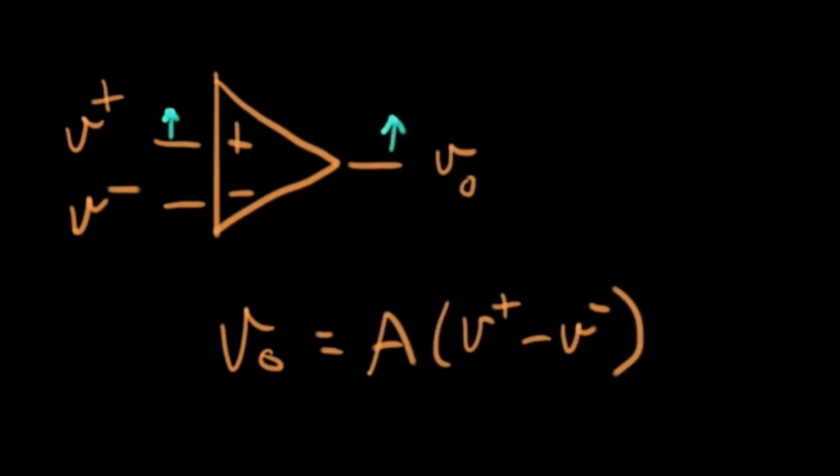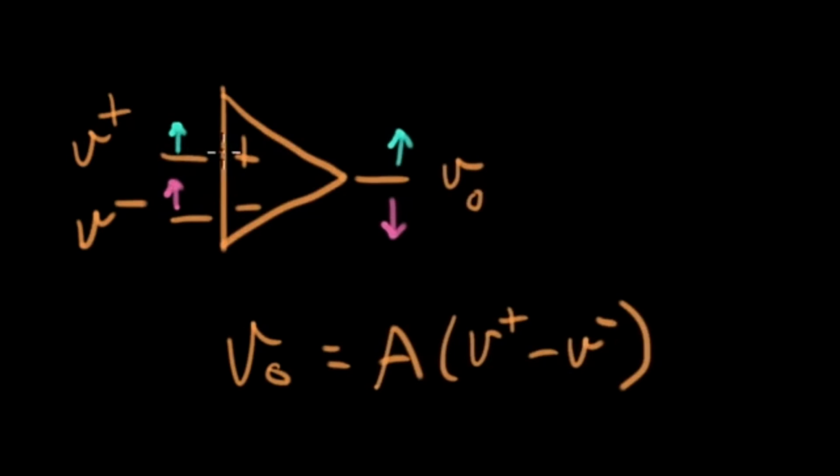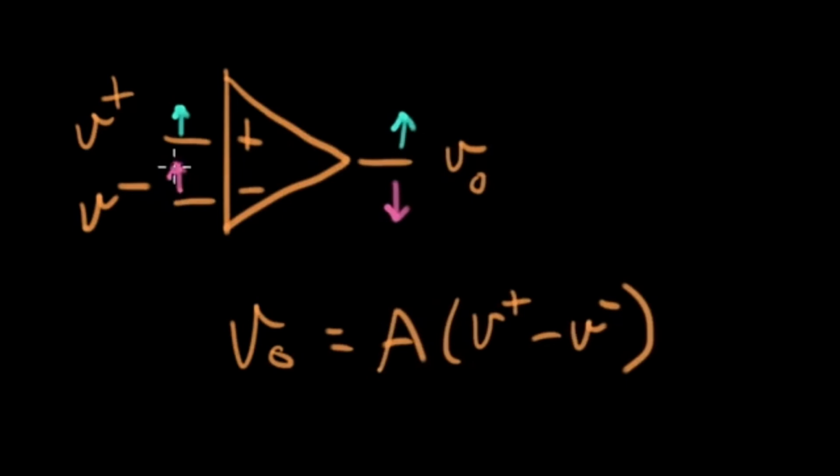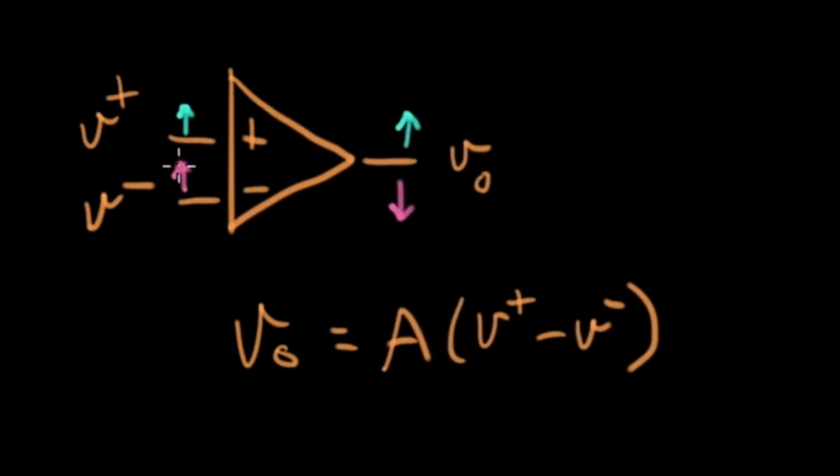This is a plus 12 volt supply as well, connected together in the node, and the node will be grounded as the voltage reference. The power supply will be hooked up like that, so with respect to ground there is minus 12 volts and plus 12 volts, and ground is in the middle.